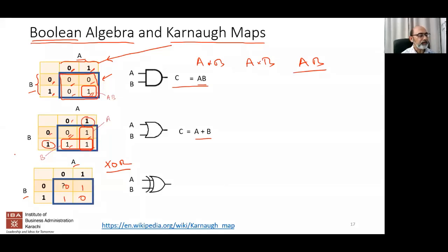The only difference between the OR gate and the XOR gate is this term over here, that when both A and B are 1, then you want the output to be equal to 0. Okay. In other cases, it's going to be in both of these cases going to be a 1. So now, how do we represent that as a Boolean expression?